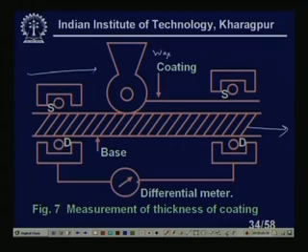You can say that the principles which you have used for the thickness measurement of the rolling sheet can be utilized, but if I utilize that principle, there will be chances of a lot of error, because the thickness there is quite high, a few centimeters, whereas here it is a few millimeters. So, I need some differential arrangement. I have some output here, and if I get this one, I will get some output. Obviously, this output will be less than this output. So, this output will be higher and this output will be lower. So, I will get a differential output. That can be calibrated in terms of the thickness of the coating of the wax. Clear?